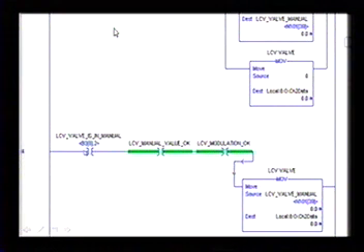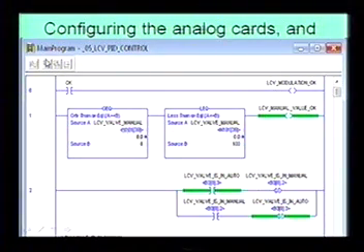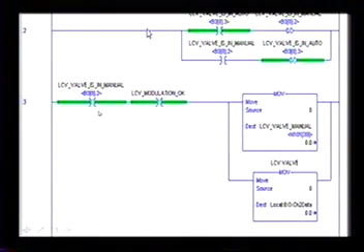And then if I am in manual mode and it's okay, I've got a valid signal up here. I'm within that range, greater than 0 and less than 100. That's a valid signal, so I say it's okay. It's a good value. And why would I even say that? Well, I do it because you don't know if the OIT is going to squirrel out on you and give you some bogus value. And this prevents you from sending that PID a signal that it shouldn't have,